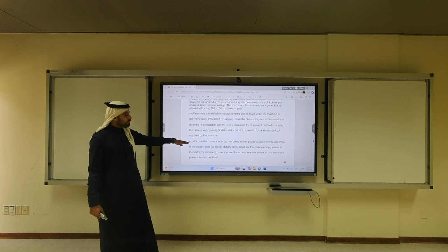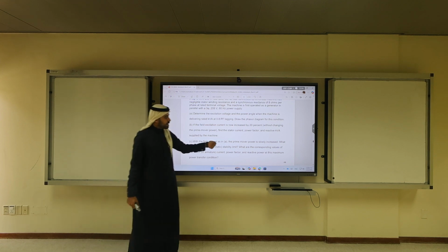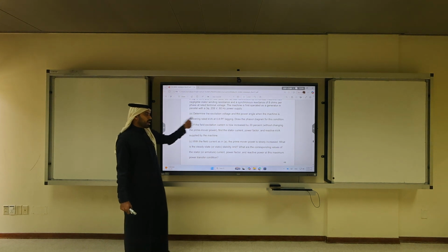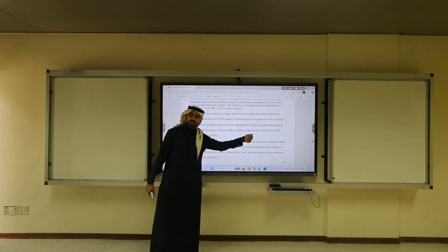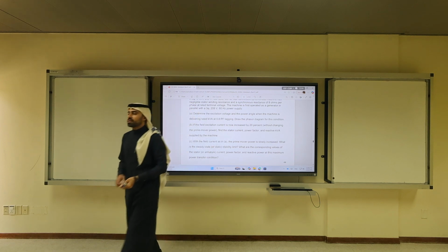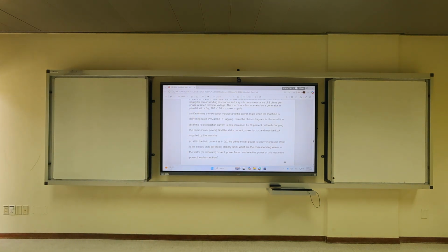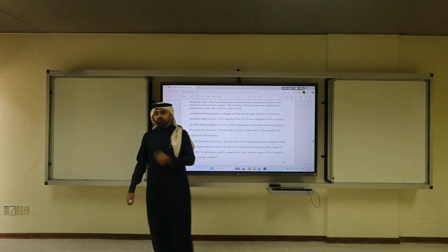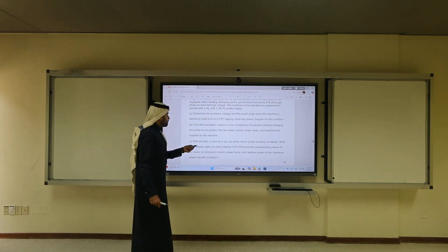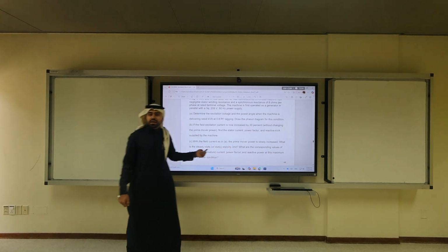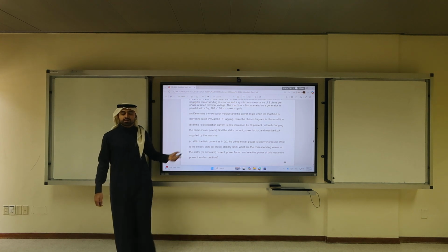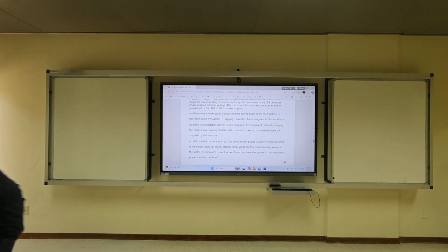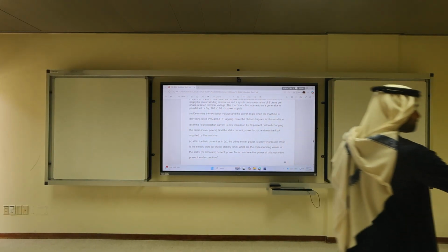In part 3, what did we have? We said we're going to increase the field current. In part 2, if we increase the field current by 20%, EF will increase by also 20%, correct? Then, the last part, we started to increase the real power. If we increase the real power slowly, it was asking about the stability limit. Stability limit: delta equal to 90.